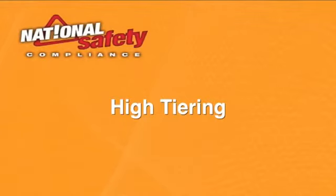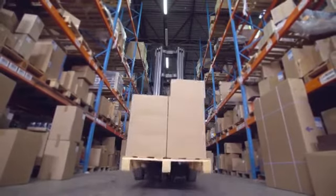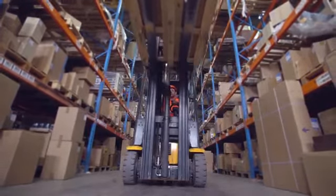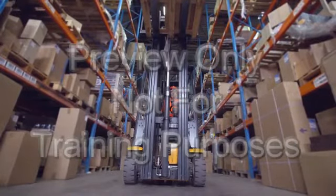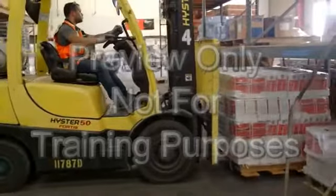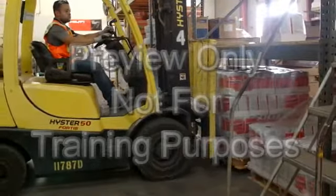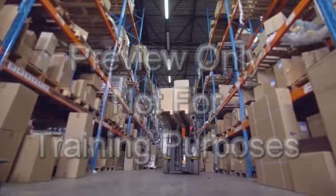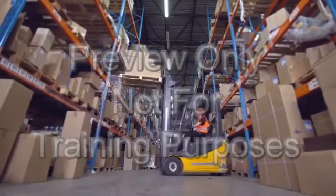High tiering. Reach trucks are often used for high tiering, which involves stacking loads in multiple tiers high off the ground. This is common practice in large warehouses with multiple large shelving units. The heaviest loads should be on the bottom tier and the lightest loads on the top tier. Reduce the load below capacity of the reach truck as the mast is fully extended.